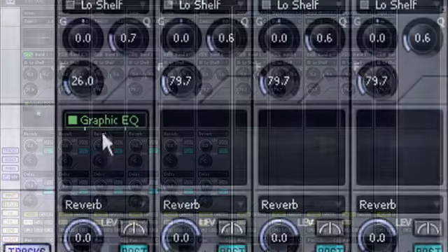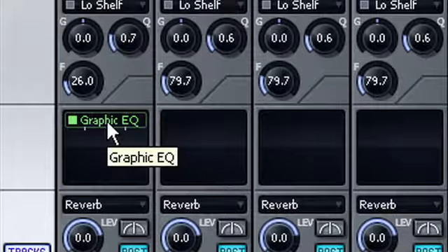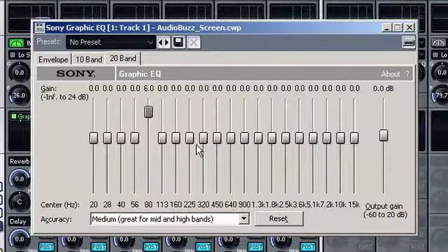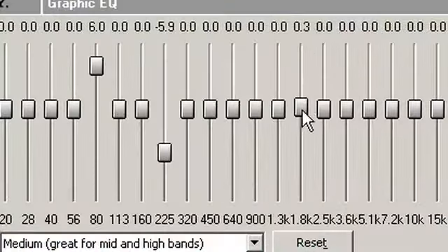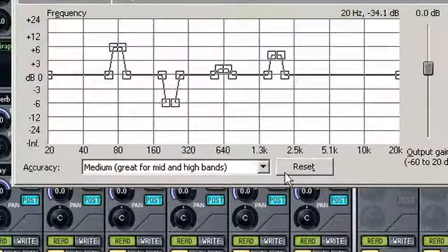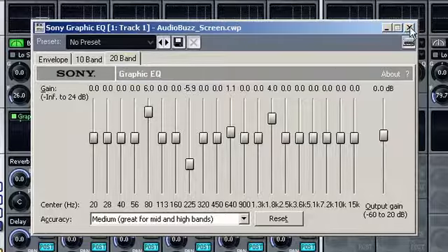One very common type of equalizer is the graphic equalizer, which consists of a bank of sliders for boosting and cutting different bands or frequency ranges of sound. Normally, these bands are tight enough to give at least 3 to 6 decibels of effect for the neighboring bands and cover a range from around 20 Hz to 20 kHz, or the range of human hearing.